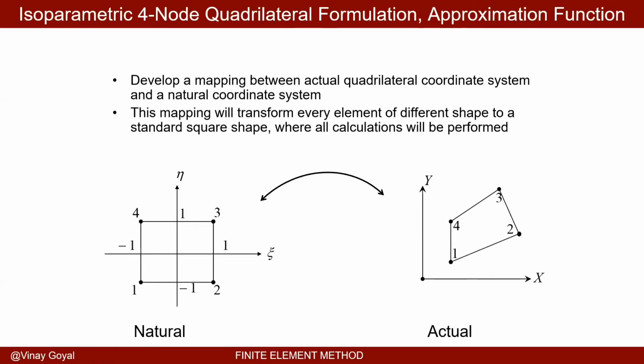If I think carefully, every element will have the same shape functions. Every element can be integrated from -1 to 1 and -1 to 1. If I can actually perform this mathematical miracle of taking every element and transforming it into this element, which I will call the master element, that'll be very powerful because the shape functions for every element will be the same. The integrals will be defined over the same domain.